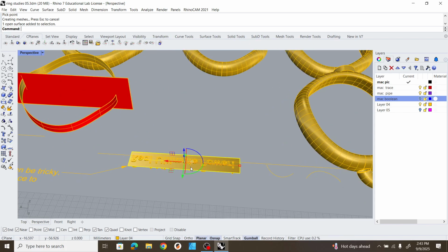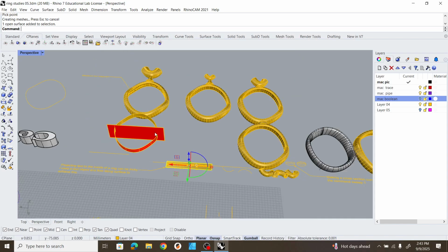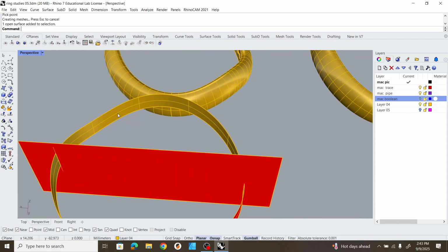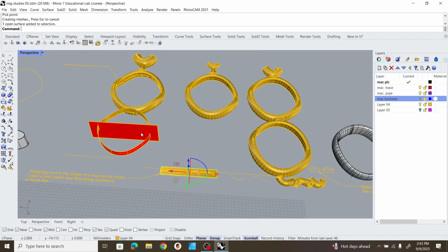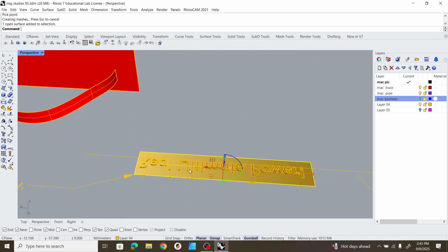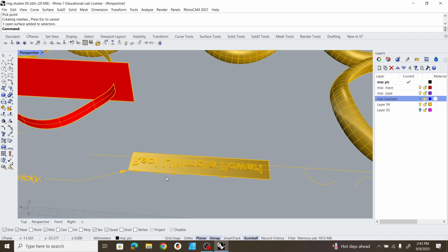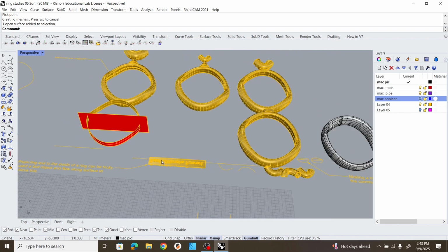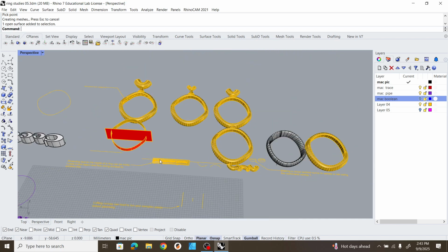If it's intersecting into my base surface, it's going to intersect into the surface I'm flowing it on. Okay, so I have that set up. I found out I had to reverse the text so that I'm looking at it right like this, and it's going to flip up onto that surface, just like that.